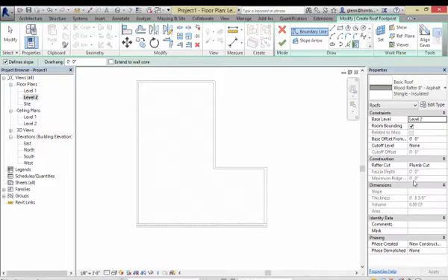Another variable you can play with is the notion of overhang. Do you want it to be right at the edge of the wall, or do you want to overhang it 1 foot or 2 feet, something like that? I'm going to put in over here for the overhang, say 2 feet, 2'0", kind of as a nice standard one. I'll put that all around. Later, we're going to learn that it really makes good sense to have different overhangs on different sides of the building relative to the sun and what we're trying to do. But architecturally, it's often easy just to do this too.